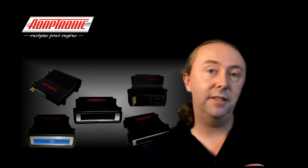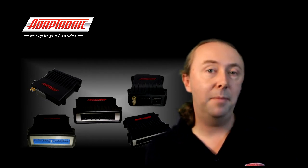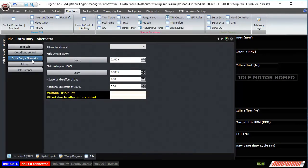Now if this value is below the target idle speed, then it won't change the target idle speed at all. So it's a maximum function, if you like. Now the extra duty alternator function is for cars where the ECU is able to see the alternator field current.